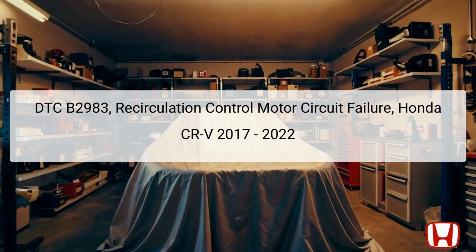The Diagnostic Trouble Code B2983 indicates a malfunction within the recirculation control motor circuit. Associated components like the linkage, door, or motor could be involved. This error can activate the DTC indicator on the climate control panel, showing as either BB6 or 57, depending on whether the display is present.